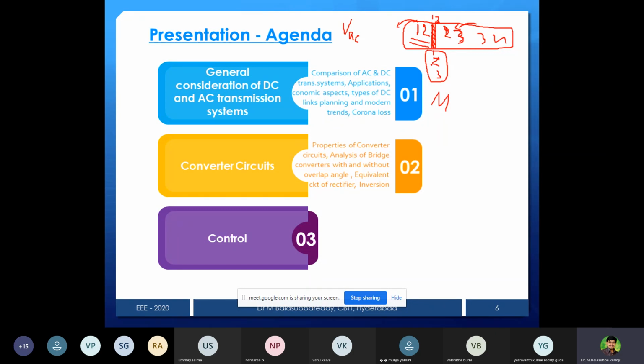Valve 1 voltage, valve 2 voltage, like that. For all the valve voltages, by plotting the graphs we can notice that they are entirely different from the previous power electronics graphs, because this overlap period is very sensitive. Based on the value of the overlap angle, the voltage is going to fluctuate, and that will affect whichever side, whether it is the rectifier station side or the inverter station side, or which valve it is going to jump that voltage from one level to another level. All that scenario is going to be observed in this.